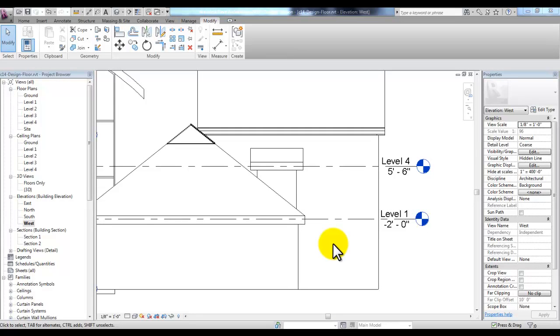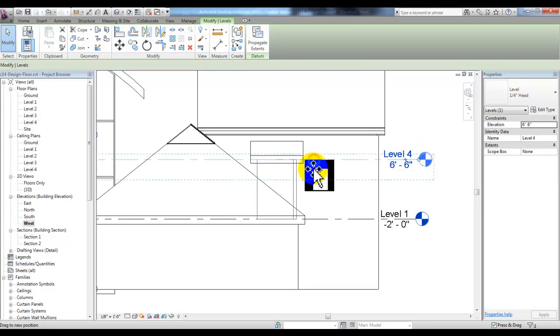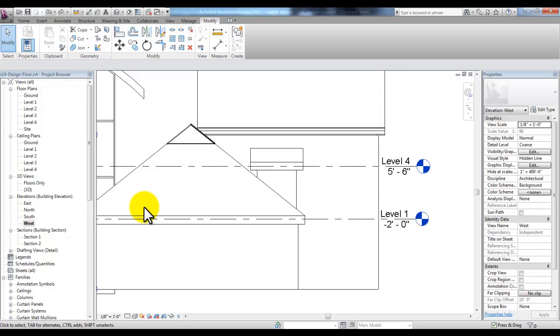And the last thing I'd like to show you here about roofs is similar to an example in the book, placing a dormer. I created walls on level 1 and established a new level that I could adjust if I needed to adjust the height so that it would clear this other roof here. And then I did change the roof slope to a 6/12 instead of the 9/12 for the clearance.